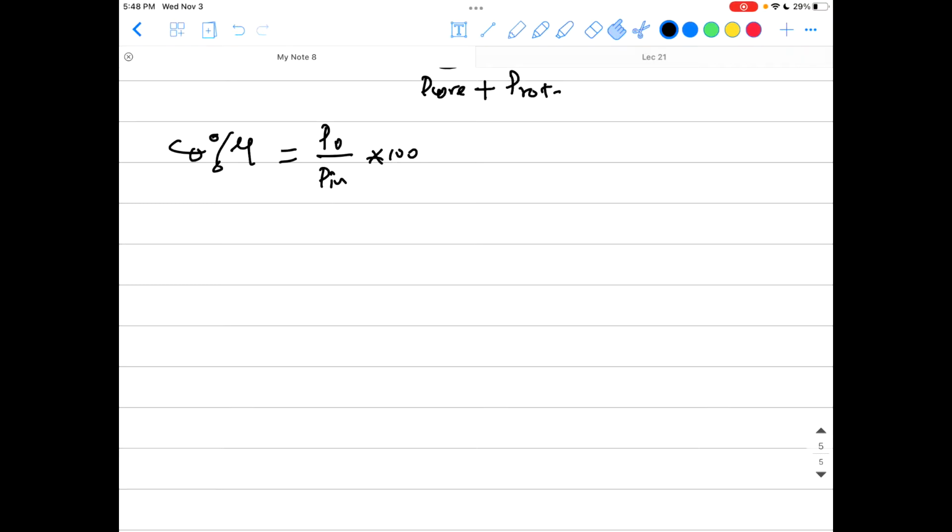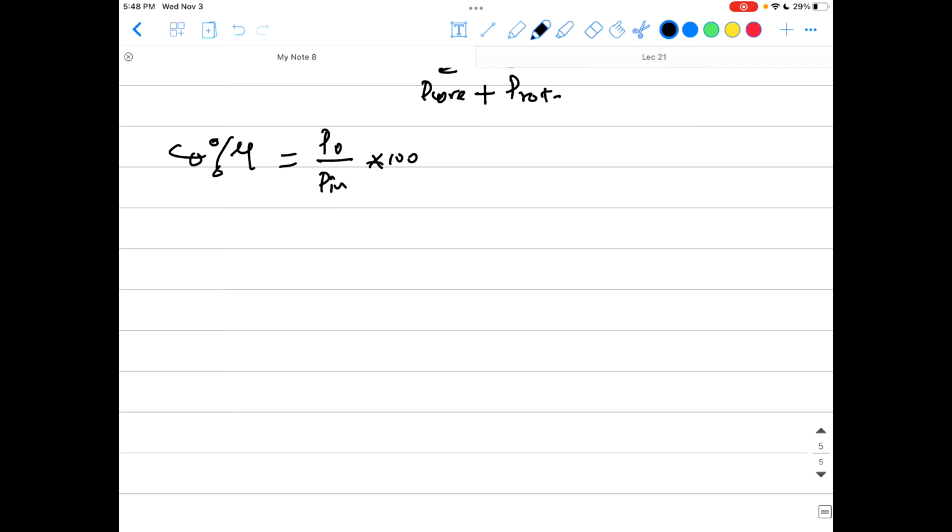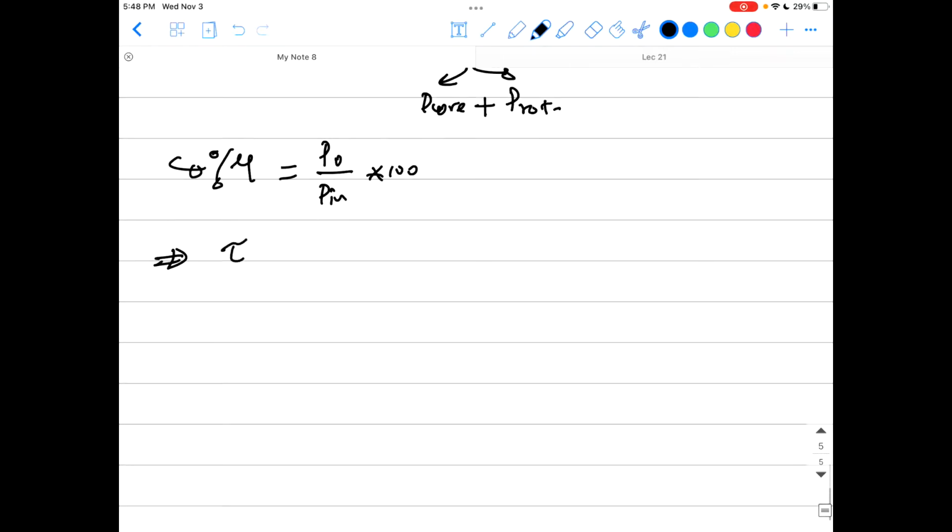Speaking of powers, we can also find out the torques. Just like we did before, the torque of the machine, we call it the motor torque. Sometimes we call it the torque developed. So it is the developed torque or the motor torque, it's all the same thing. It is basically the converted power or the developed power, they are the same thing, divided by omega m, like any other machine actually. Okay, guys?